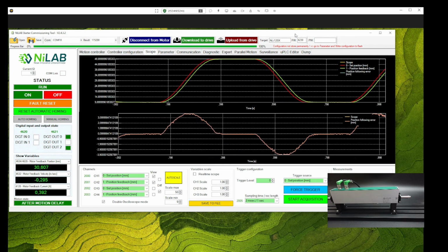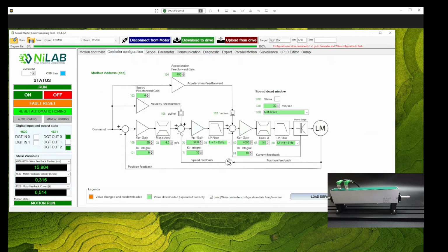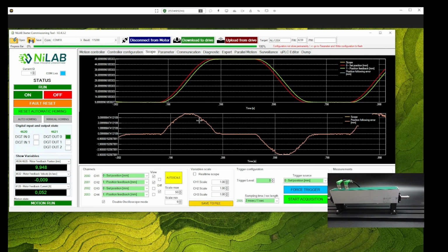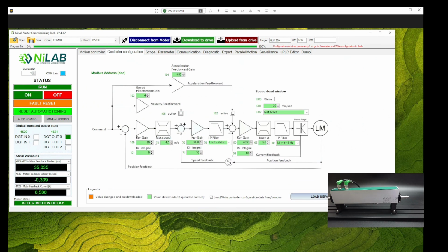At this stage, we have a fundamental tool at our disposal, velocity feed forward, which serves to minimize the lag between the theoretical and actual curves. Currently, the error is significant, as seen by the gap between the two traces. The first step is to increase the position gain from 50 to 80. While this intervention would already reduce the error, for an optimal result, we will activate the feed forward, initially setting it to 10. We then reacquire the signals.